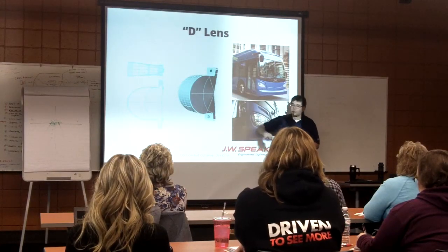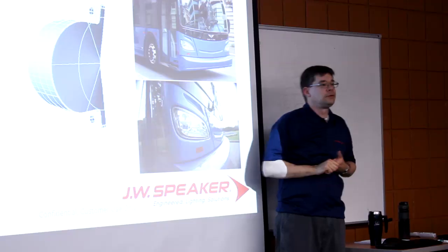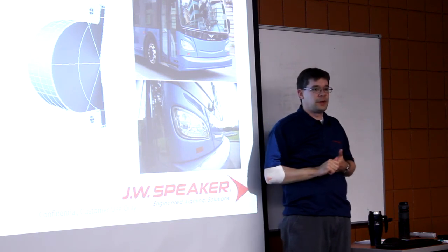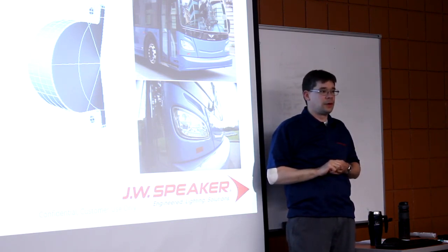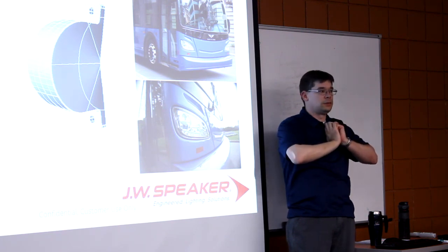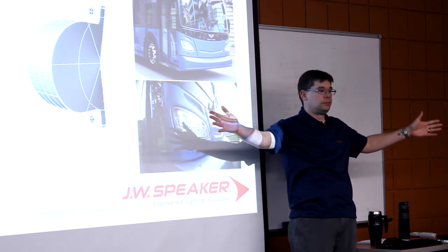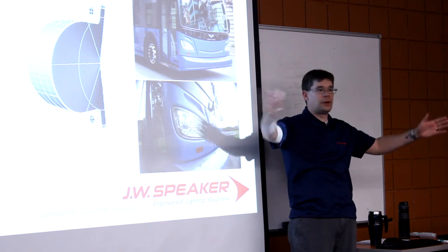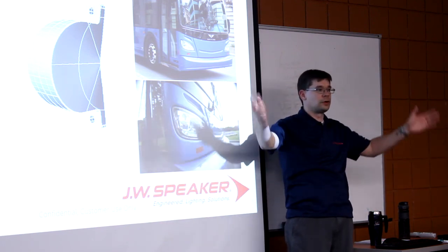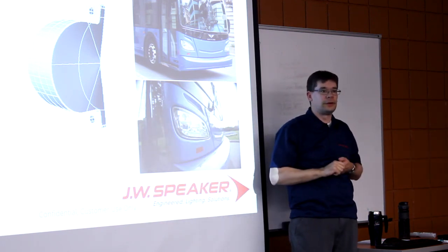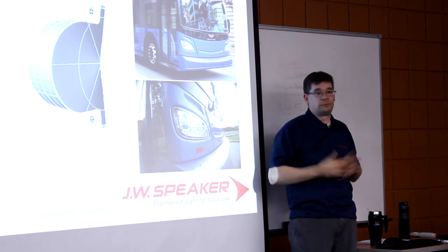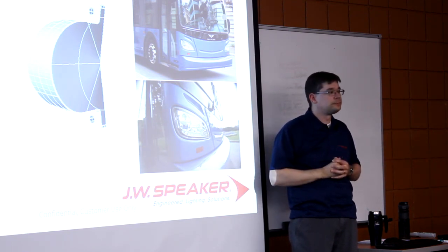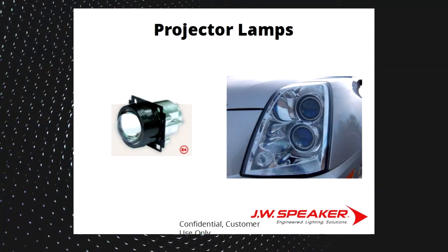and from the side profile kind of look like a D. So that's where the very original name came from. And basically what these optics do, and why we use them in our headlights, is they make a widespread uniform pattern. So it spreads out wide and has a nice curve at the bottom, and that lends very well to creating the spread that we need for on-road lamps.